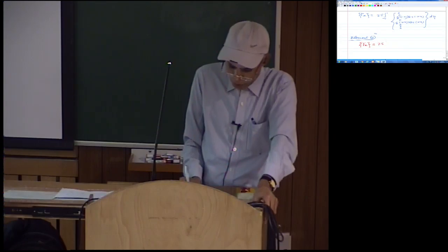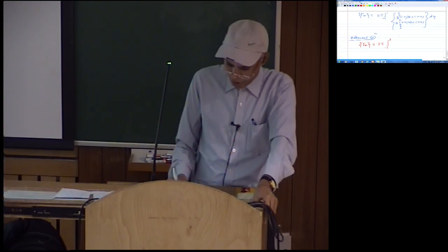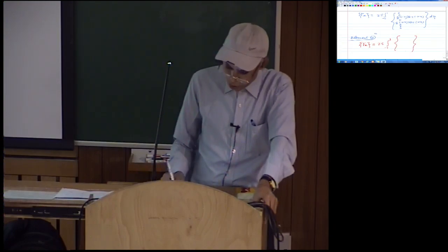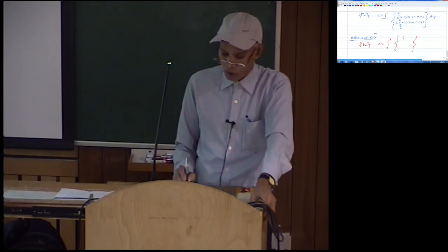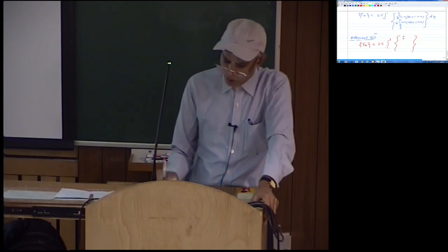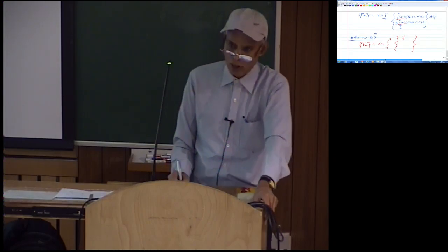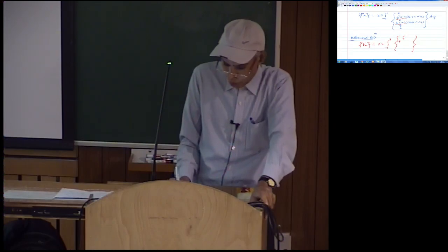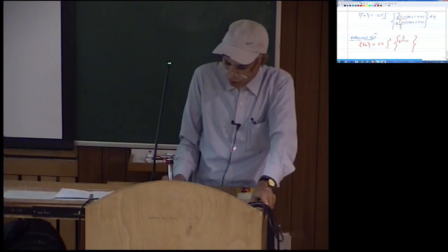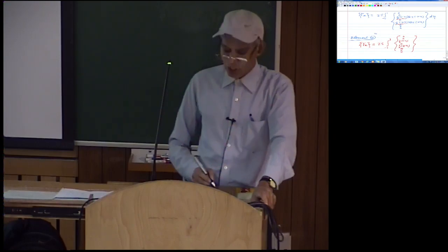So that 2.5 you can keep here, and then this is -1 to +1, and the same thing, only n2 and n3 are going to be non-zero, so the first two terms would be 0 in terms of local coordinates, and the values of the shape functions are also going to be 1 by 2 (1 minus eta) and 1 by 2 (1 plus eta) for second and third nodes of the second element in local node numbers. So this would be 1 by 2 (1 minus eta) into y, of course has to come, 0, 1 by 2 into (1 plus eta), and then of course 0 0 0, and then into y.